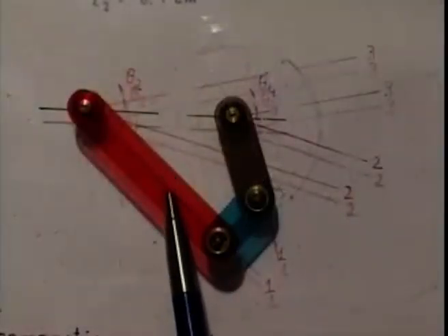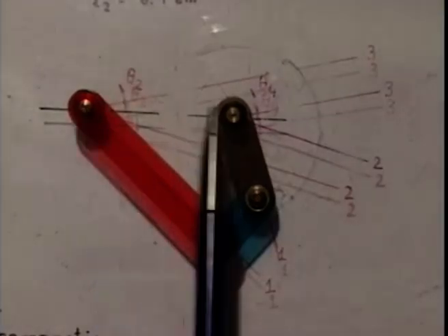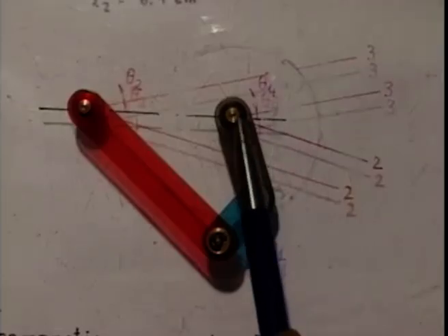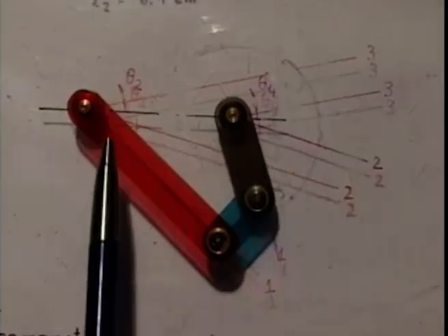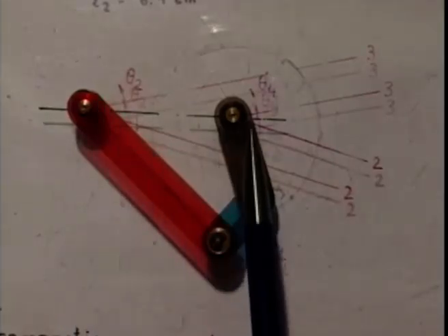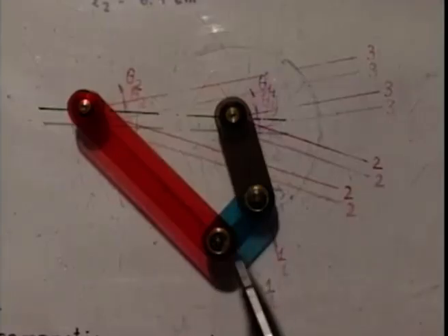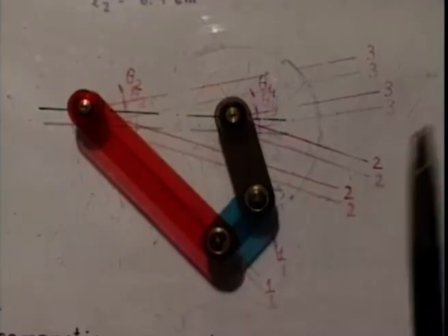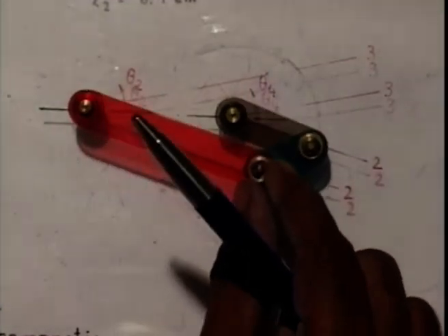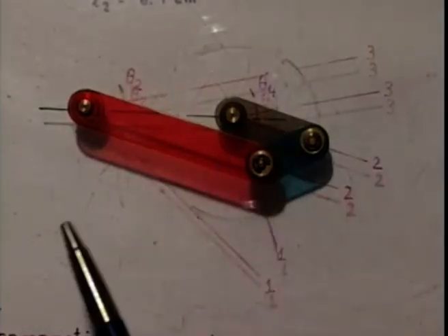This is the model that we get for the solution to this problem by graphical method. This is O2, this is O4. This is minus 48 degree and this is whatever O4 makes. We have got L2 as 6.4 centimeter and these are the other link lengths. This is the mechanism at the first configuration, satisfying. Now, if we move this linkage, these are the desired second configuration which is being taken up by this linkage.